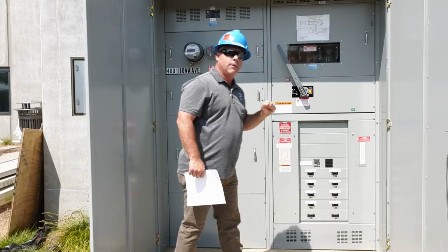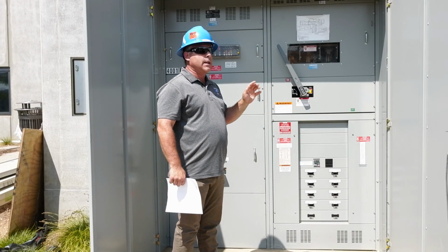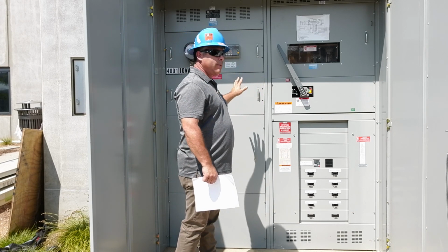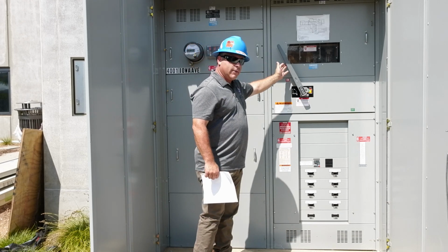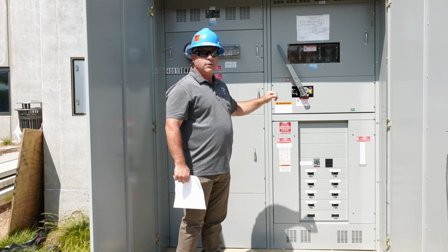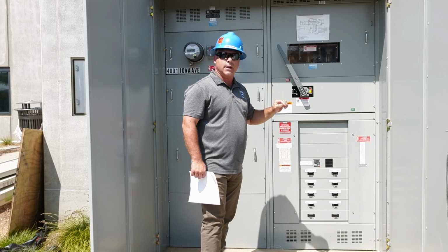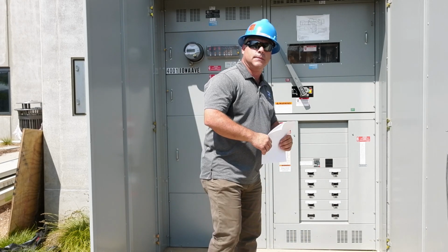If the fire department needs to turn off anything in an emergency, disconnect any inverter from the distribution board and take it away from utility so nothing is going back on utility, either they turn off the air switch or they turn off the breaker. These panels are all located and there's placards showing where everything is in place. Now we're going to move on to the monitoring area.